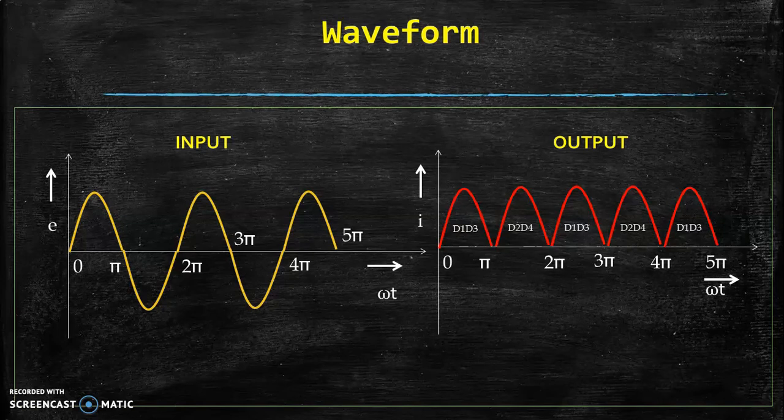So it is a continuous rectification process. During both cycles, conduction takes place. In the load, we have unidirectional current. We get output voltage, that is DC voltage, across the load resistance, unidirectional. So we can say that we have converted our AC supply into DC supply.